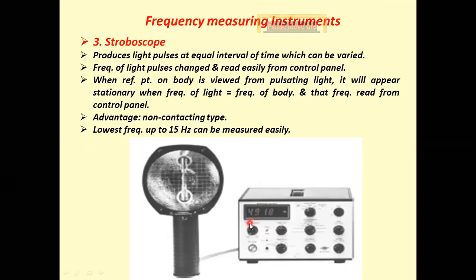So the light appears stationary when the frequency of the pulsating light is equal to the frequency of the vibrating body or system, and when that happens we have to read the frequency from the control panel.